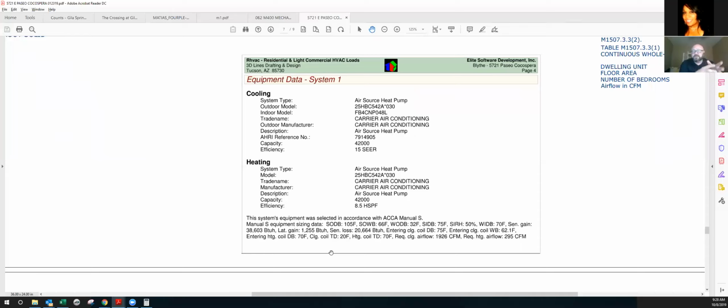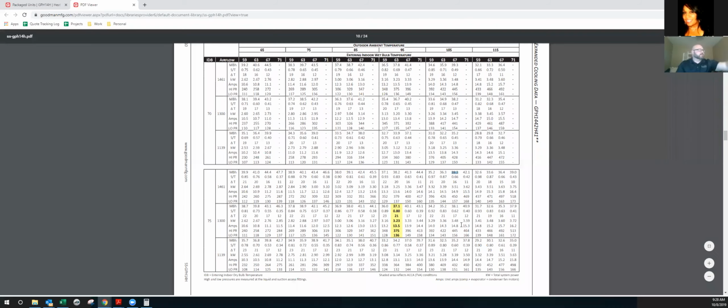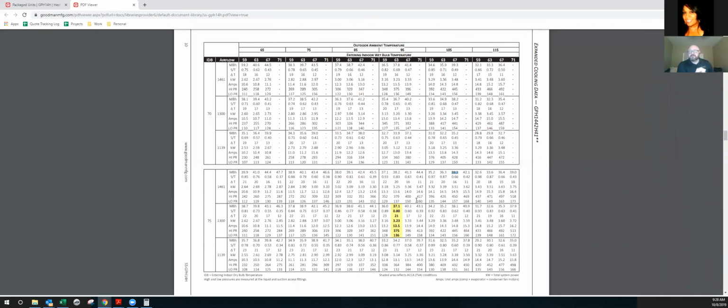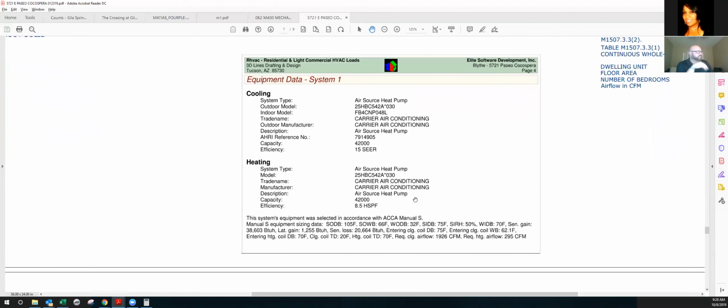Latent cooling is what just kind of disappears. You get no real value out of those BTUs, and that is affected by a number of conditions, by those design parameters we were just talking about. The amount of BTUs that you deliver that actually affects the temperature is called sensible, because you're actually sensing it. It actually has an effect on the temperature of the room.